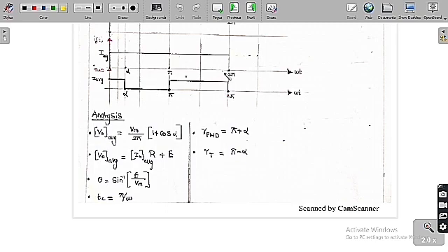So finally if I draw the thyristor voltage, it will be like this: a positive pulse, again 0, and again a negative pulse. Only for an angle of pi do we get a negative pulse, so the time is pi by omega. Therefore the circuit turn-off time is equal to pi by omega, since only in this region do we get a negative voltage across the thyristor.